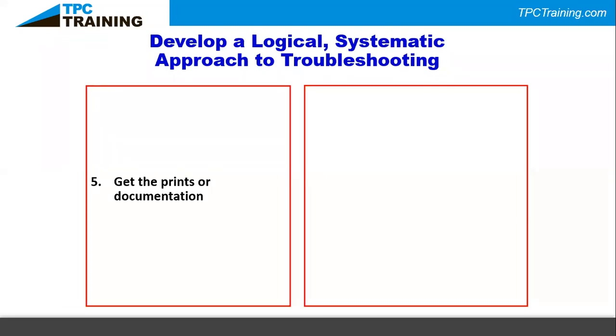So if you think about it this way, both of those tools can have different levels of quality, right? On the meter side of things, whether on the mechanical side, you're going to be doing some vibration analysis or looking at infrared or heat, or on the electrical side, you're going to be testing voltage or current or resistance. The quality of that meter matters.